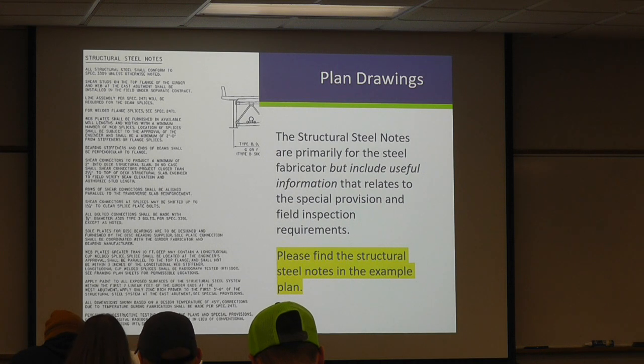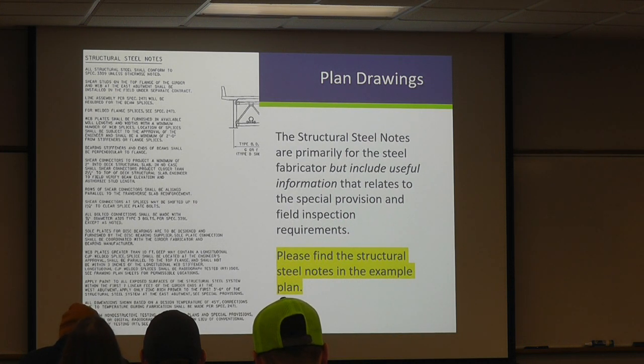Your plan drawings are going to have a lot of structural steel notes. Most of these notes are geared or directive towards the fabricator on what they're supposed to be doing, different conditions they have to meet. But there's going to be some useful information that relates to the erection of these beams that you're going to have to understand as a field inspector.